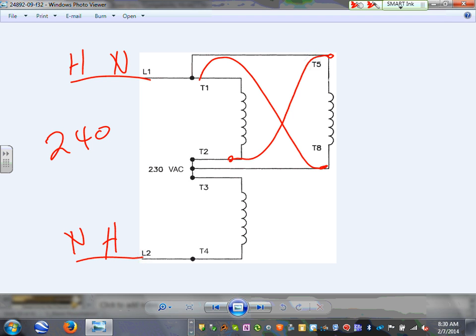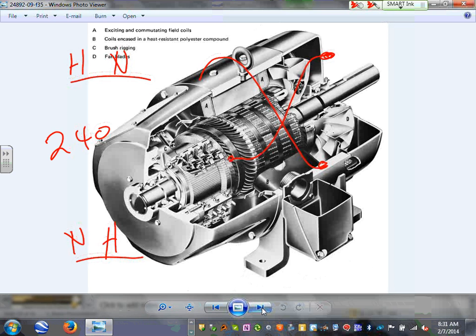If it was a three-phase motor, there's no neutral. If you flip the phases, the motor will go the other direction. So in a single-phase motor, you don't have to worry about which side the neutral is located, all right? But you really have to go disconnecting internally in order to reverse it. And we have a couple of methods, guys, of reversing a three-phase motor. Okay, so that's the connection for clockwise and counterclockwise.